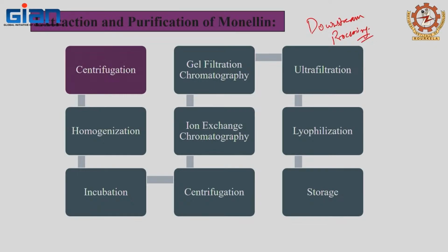Next, after centrifugation, as our product is intracellular, we need to break the cells to extract our protein. For this process, we can use a homogenizer. A homogenizer pressurizes our feed and impacts it on a metal plate, so the cells rupture and our protein gets into the media. YO Cell Bio is one company that produces homogenizers. They have a feed rate of 120 to 150 liters per hour, work at 1800 bar pressure, and the power required is 11 kilowatts.